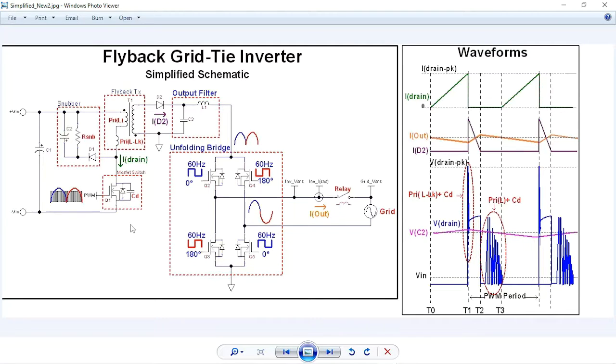So let's talk about how it actually works. On the PWM side, you have a PWM signal being modulated by this half sine. So on any given pulse here, when this pulse rises and goes high, it turns on the MOSFET. When the MOSFET turns on, current flows from V in through the primary, through the leakage inductance, through the MOSFET, and back. So that's your current loop.